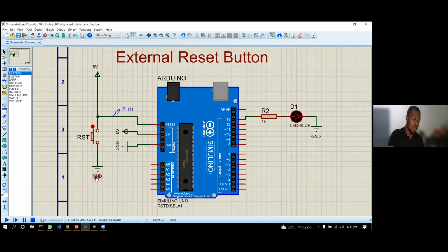So in order to prevent the short circuit, that is the reason we put in a very large resistor here, because technically we don't need current flowing through here. Now, ideally, you can make this as huge as possible, but usually I just throw in a 10K and that does the magic for me. So this 10K makes it possible such that if I close this circuit, we don't have a short circuit on this line. So I'm going to simulate this.